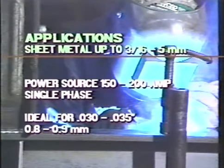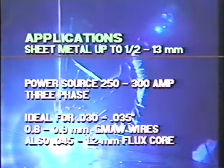Applications. If welding up to 3/16 of an inch, a 150 to 200 amp single-phase power source is sufficient. .035 wire is the most practical choice. A 250 to 300 amp power source is practical on metals up to 1/2 inch. This is typically a 3-phase power source.